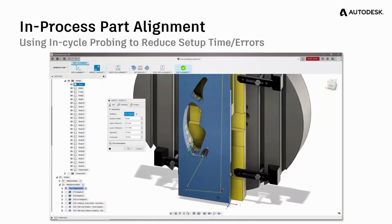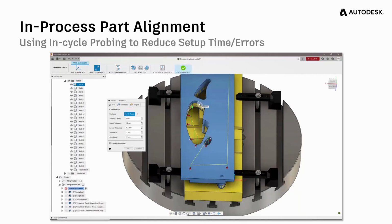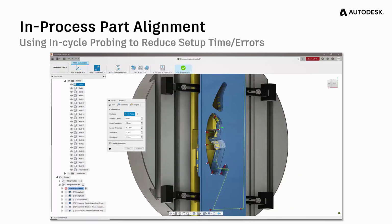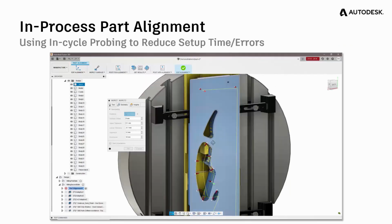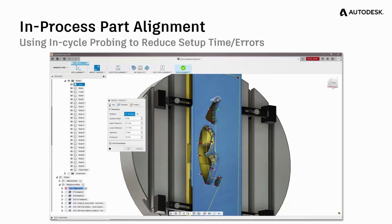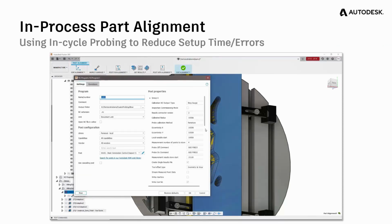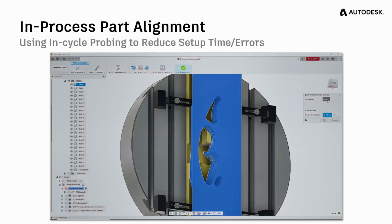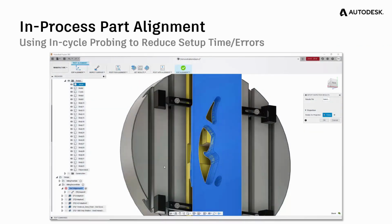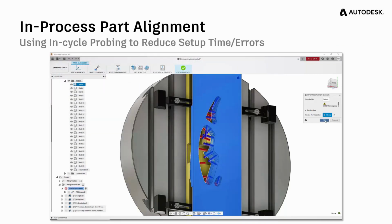Now, once those probe paths have been defined and the NC program has been output to the machine, it can be run. The machine then generates a series of measurement points as a text file, and that text file can then be re-imported back into the Fusion 360 program. Now, crucially, Fusion 360 will then display the measurements as a series of color-coded markers. So they'll be able to identify errors, and you'll see those appear in a moment. So here you can see we're selecting the measurement file, and then after a brief delay, you can see them